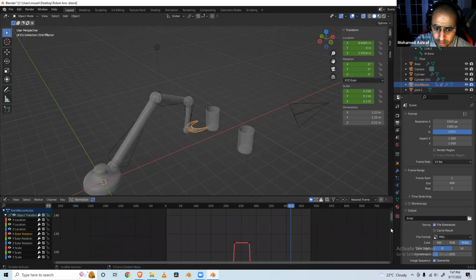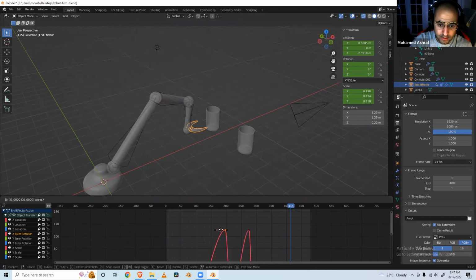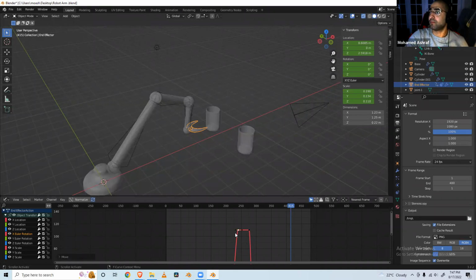Let's zoom in. What you can do is press G, just like it's an object, and move it. If I constrain it to the x-axis, then I can move it along the time. It's weird, I know. But if I also press 12, then I can extend it 12 more frames, which means that instead of having, for example, 12 seconds to do it, it has 24.